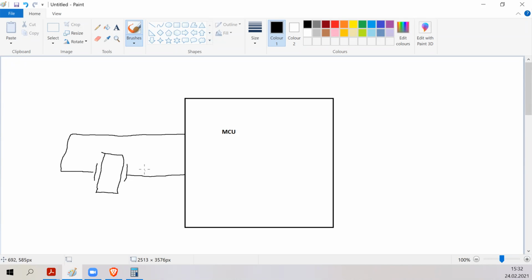So it starts to oscillate and resonates at some frequency, and its oscillation is fed back to it, so it becomes a stable oscillator. But because it has some capacitance, there is a requirement that you also connect two capacitors to ground. It's just a classic schematic. Basically, all microcontrollers require that you have the oscillator connected between MCU pins. In our case, it was port B7, for example, and port B8.